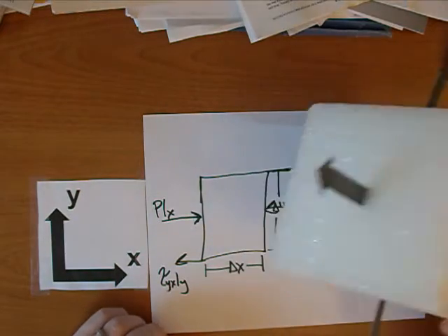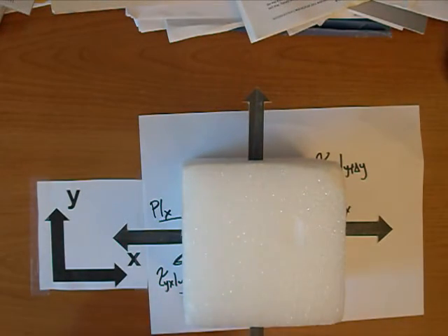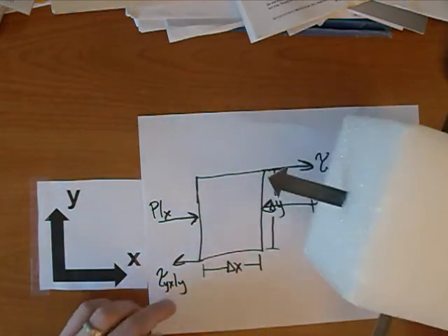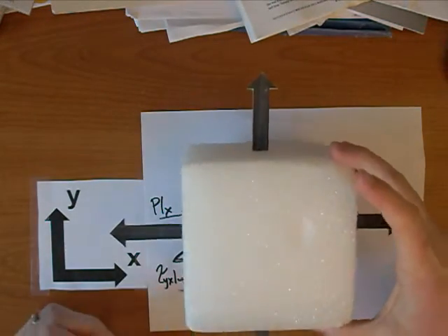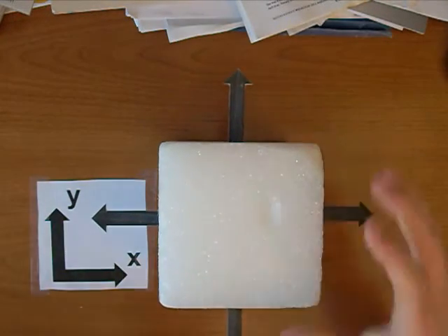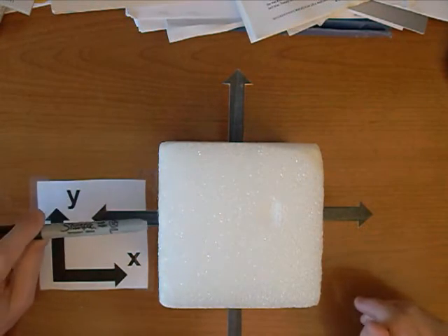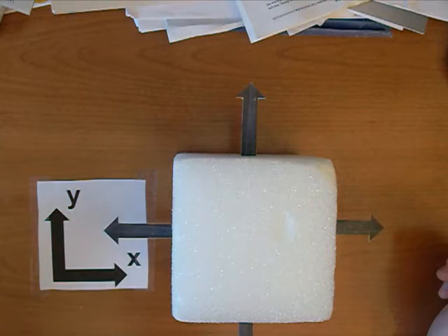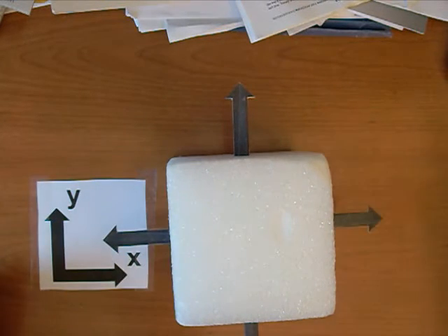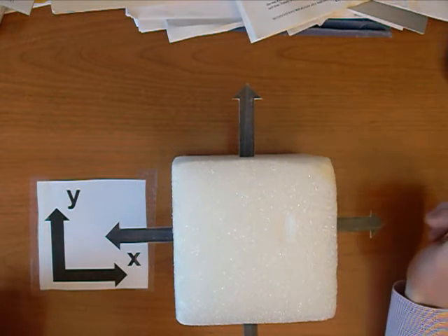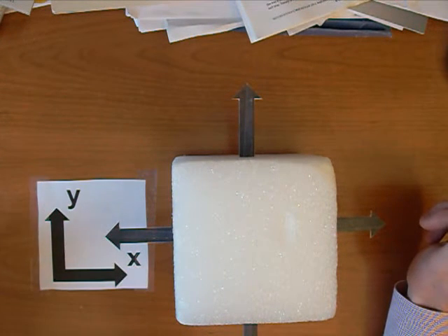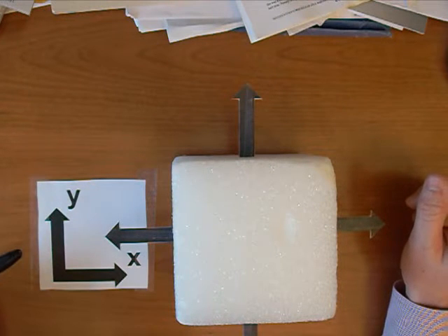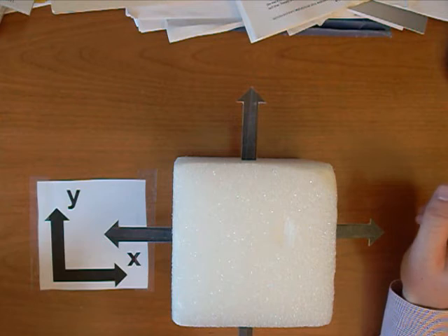Alright, so now here's a 3-dimensional cube we can use to talk about it. So this cube is basically the same as this drawing right here, and what I have here is I've made the unit outward normals for each one of these surfaces. So again, think about the flow moving through our control volume at this face and then coming out of this face. And so for the two pressures, as I mentioned before, and using the Deen textbook and how they've set it up, the pressures are going to be acting opposite of the unit outward normal.